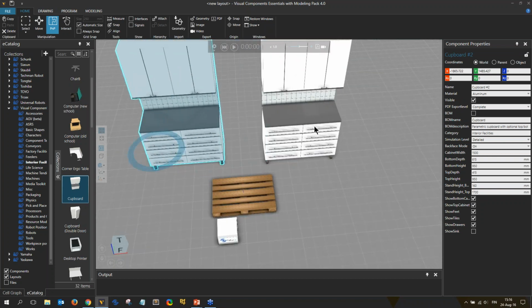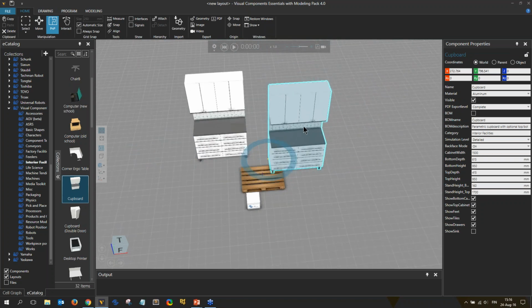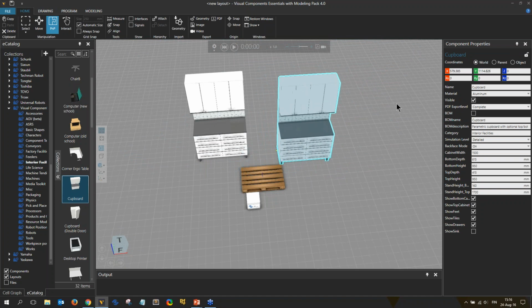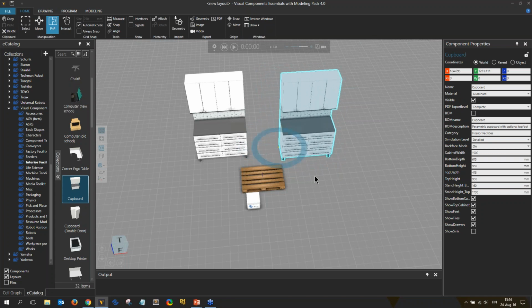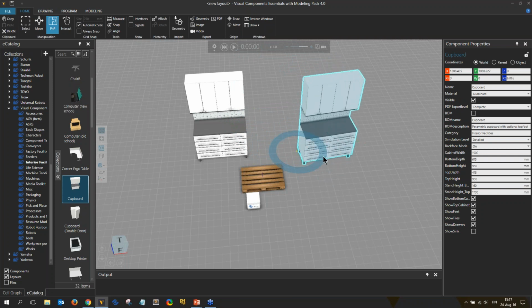So plug and play allows you to move components on the floor level. You don't necessarily need to click on the component. When I have this selected, I can click even here in the empty space and start dragging, and it moves the selection. This is by design, and it's very handy when you have a small component selected and you don't need to aim on top of that component in order to move it. Also in this PMP mode you see this little circle. If you click here, you can start rotating the component on the floor, or around its Z-axis, because this is what you typically do when you're configuring layouts. You move them on the floor and you rotate them on the floor. And as I'm rotating, I can see this little angle dial shown, and if I go on top of the dial with my mouse, I can easily go to, for example, a sharp 90-degree rotation.